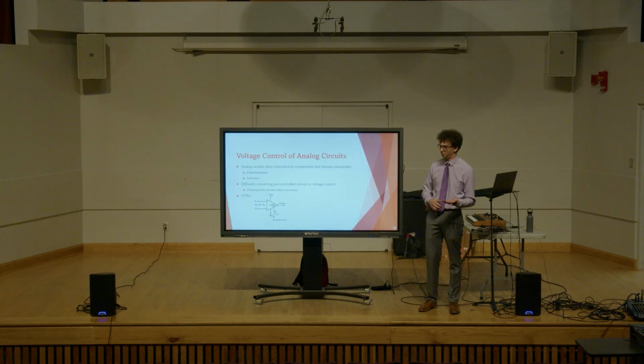If you have a bias current of 0, it won't amplify at all, it'll just spit out nothing. And if you feed it 1 milliamp, I think it's about 17 times the voltage difference at the input. So it's a fixed and sort of linear slope that you can mess around with. This has been a large turning point for me in how I'm going to implement voltage control. And you're going to see this in every circuit that I present to you onward.